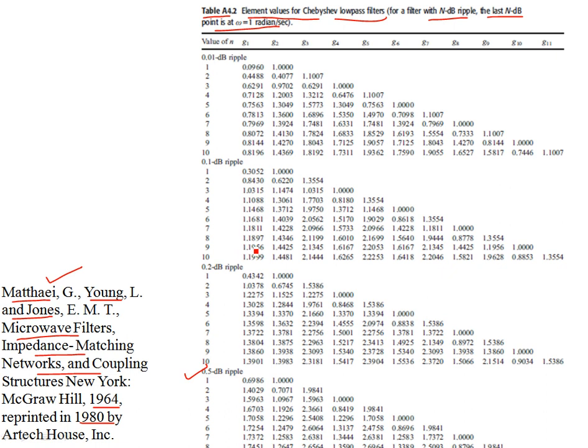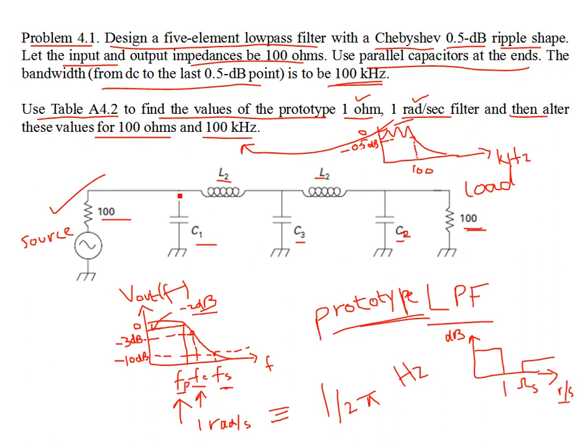Okay, so it brings some simplicity into the design, that you don't have to work out the poles and zeros on the Laplace Argand's diagram to satisfy the frequency specifications. You don't need to bother about those things. Just have a look at what is required and what is the order of the filter. Let's call this an N section filter. It simply means, according to the table, how many inductors and capacitors there are.